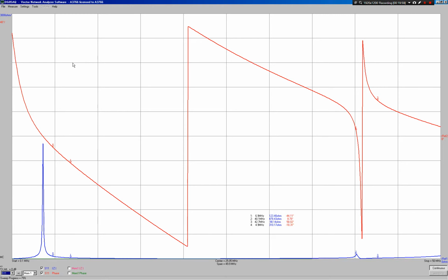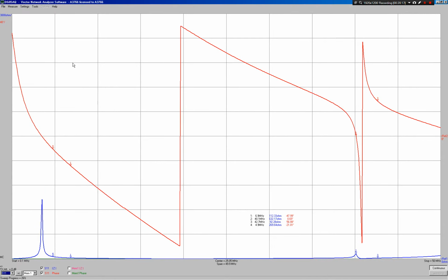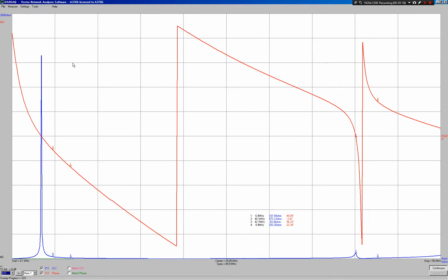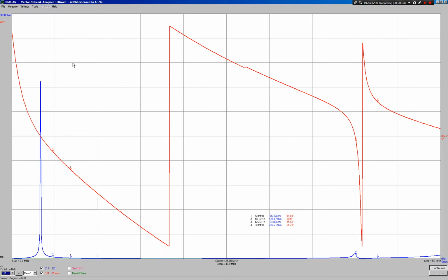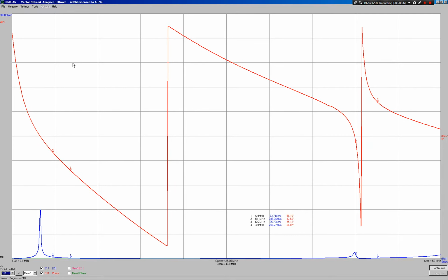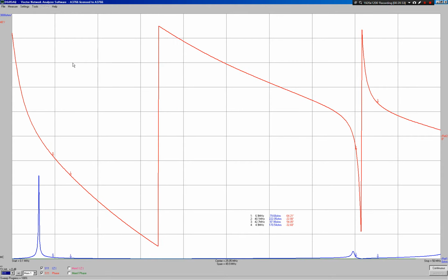And that's not that the primary resonance circuit is at the same frequency as the secondary. It's not designed in that way, where they're both resonating at the same frequency, at least not in this design. I mean, they can be set like that, but in this case, we are just loading capacitance on that parallel tuned circuit in the primary, and that will affect the tuning of the entire Tesla coil system, including the secondary. So we're still winding that capacitance down. If I have a look at the capacitor, we're still only about a third in, so we're probably at about 200 picofarads now.